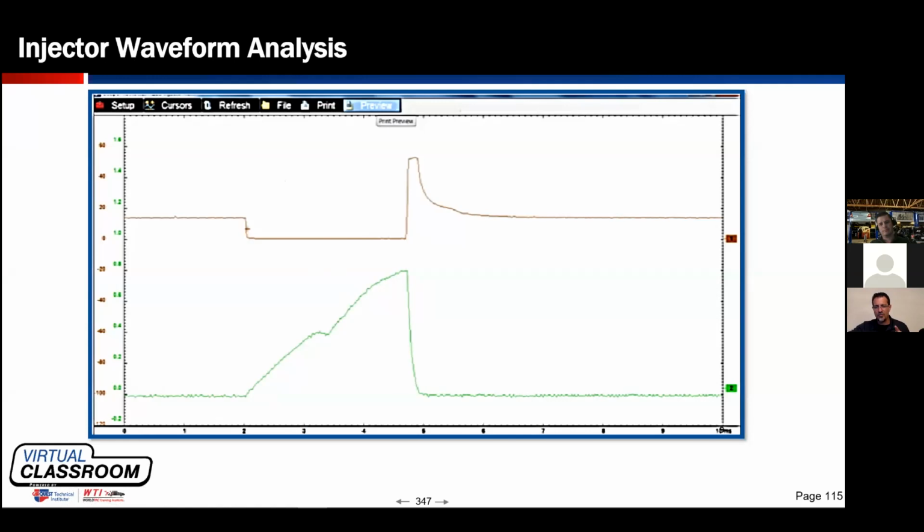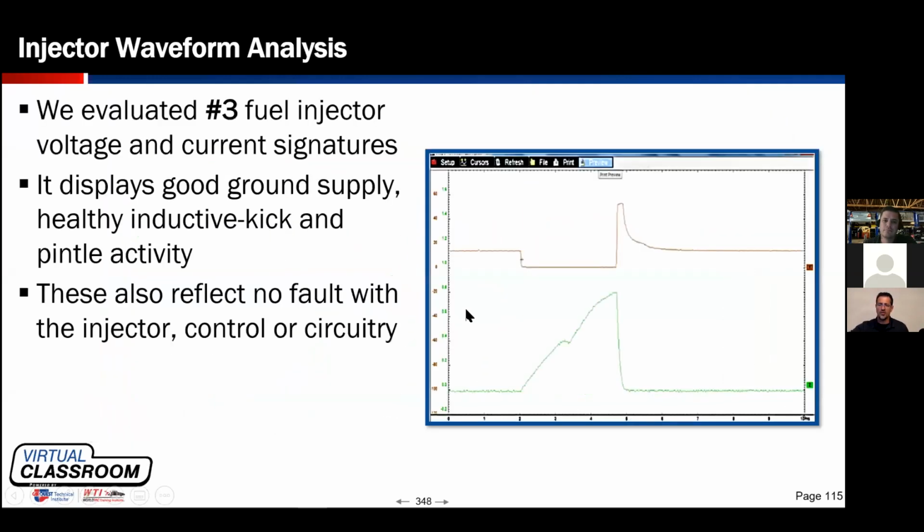But did he really prove that it's not mechanical by performing the relative compression test? What does that test tell us? It tells us a cylinder's ability to seal, right? To seal and to harness the air inside it. That's it. It does not say how the cylinder breathes. So Dave's going to commit to an in-cylinder running compression test, not because he has evidence that it's mechanical in nature, but because he has evidence that it's not fuel related and it is not ignition related.